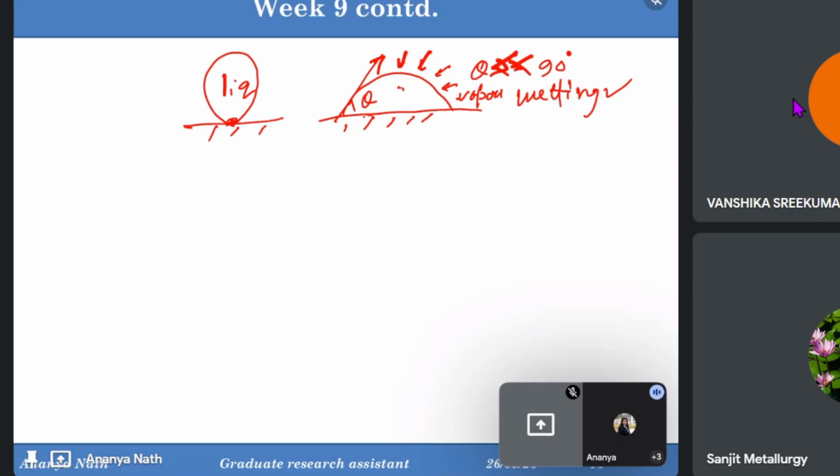So the formation of Al4C3 is influenced by alloying additions like Si, which can suppress it. As I said, Si also has a high affinity, like Ti, for making carbide rather than aluminum. So Si improves the wettability by segregating at the interface and forming a strong chemical bond with SiC. So these are some important topics when you are dealing with a specific type of MMC. When you are concentrating on aluminum and SiC metal matrix composite formation only, then you can go for this Ti or Si mixing to improve the wettability. But these are not universal for every type of aluminum alloy. You have to remember this.